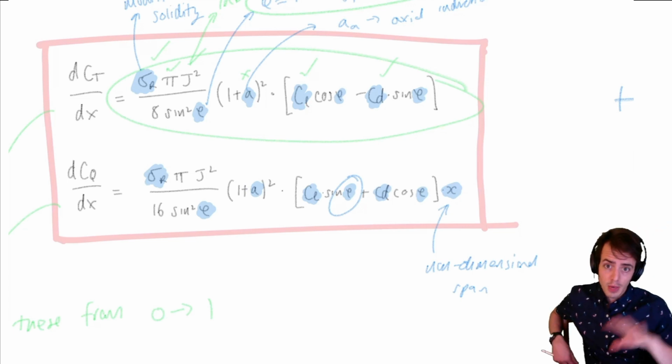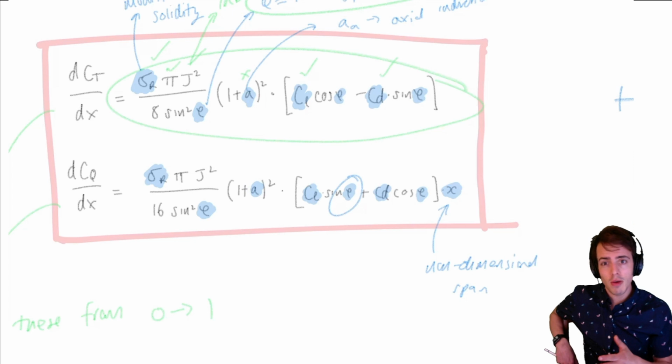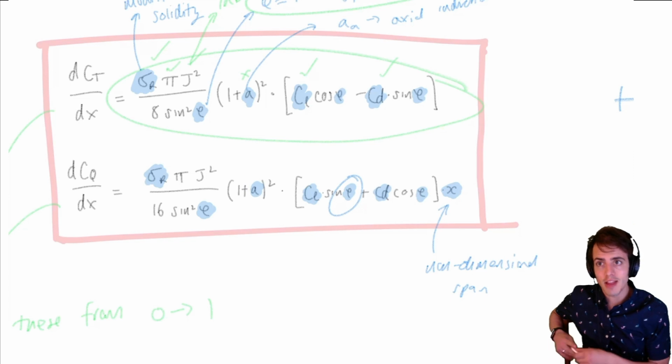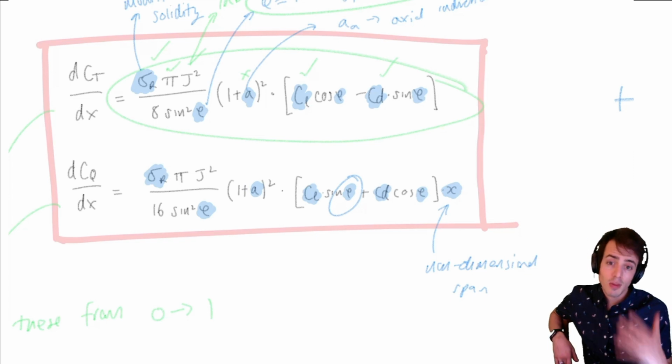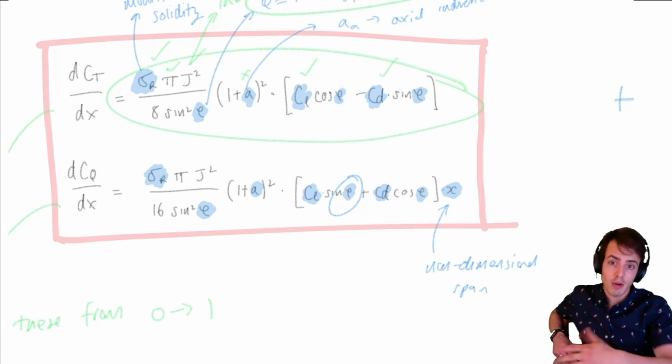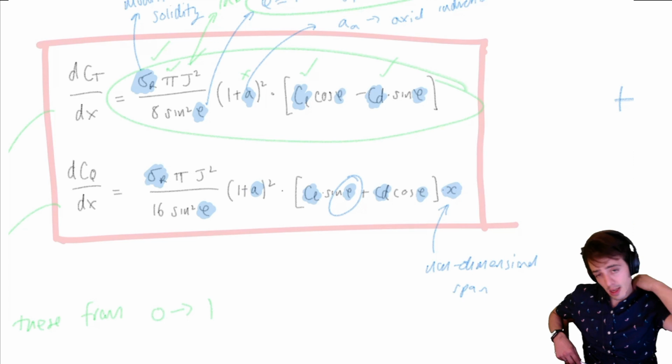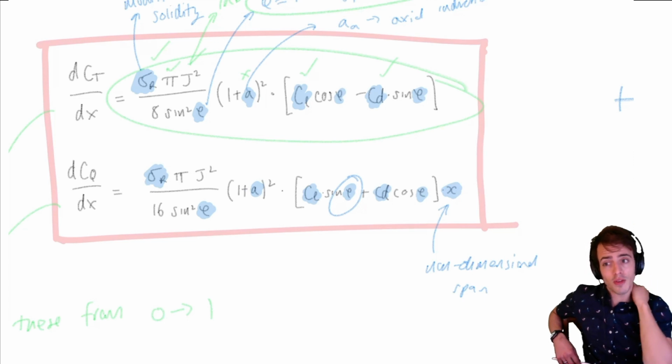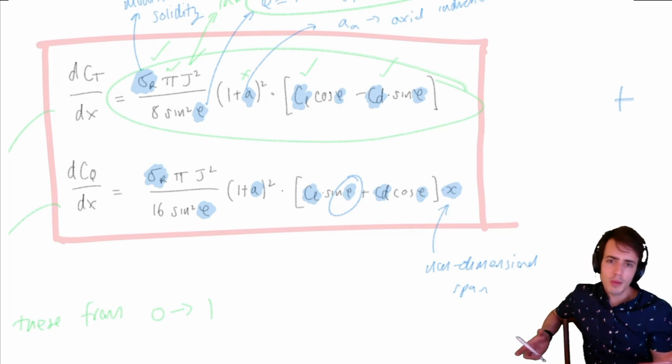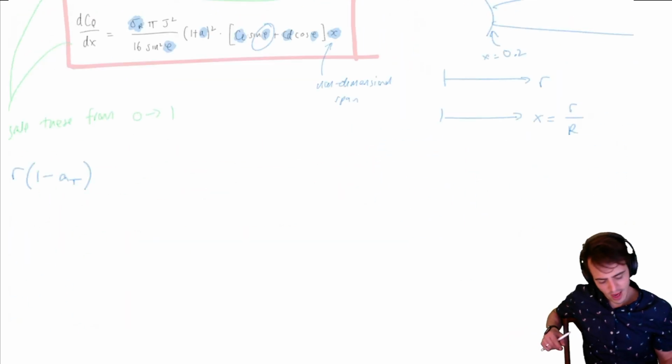So what we ultimately will end up doing is setting them equal to 0 at the beginning, and remembering that because these are nicely behaved equations, effectively we can then use an iterative solution to find and converge upon the actual value of our axial and tangential induction factors. There are smarter means we can use to solve for them. We can set them up as a system of nonlinear equations, and we can then use some better numerical solver to get the final value. But even an iterative scheme is pretty fast for these sorts of propeller calculations.